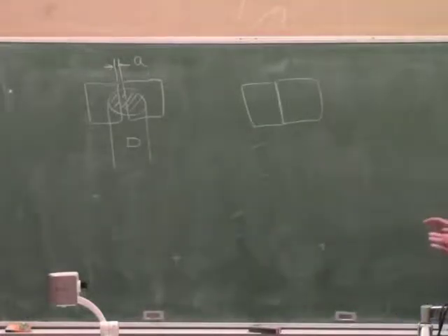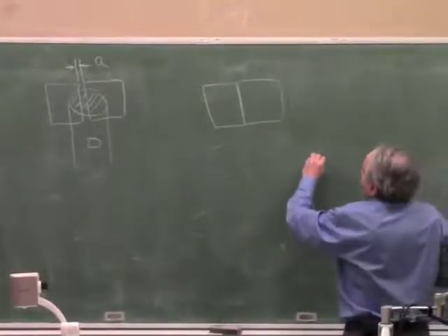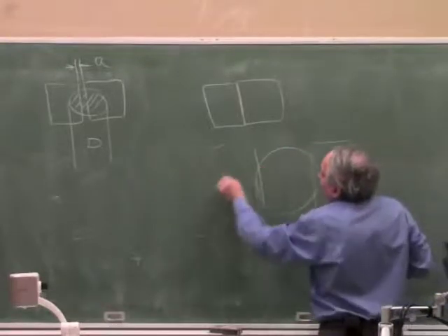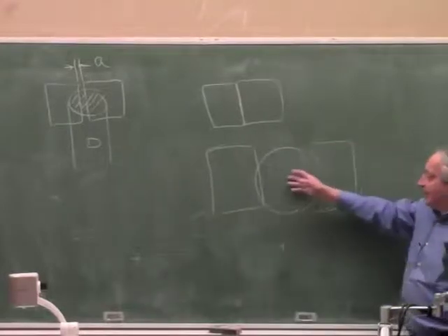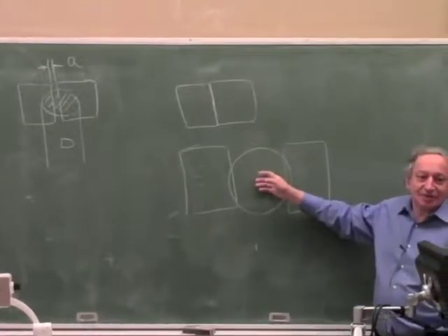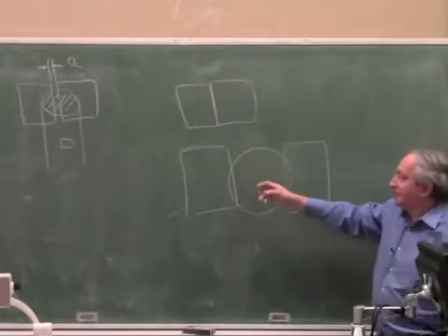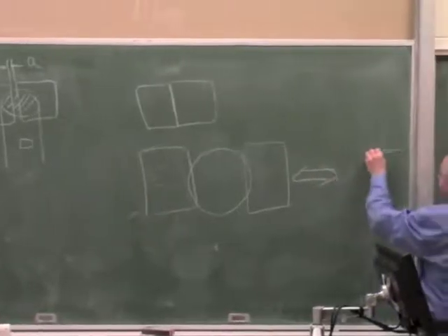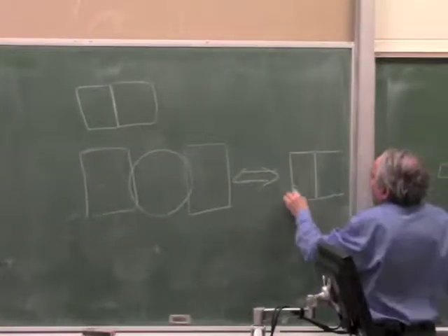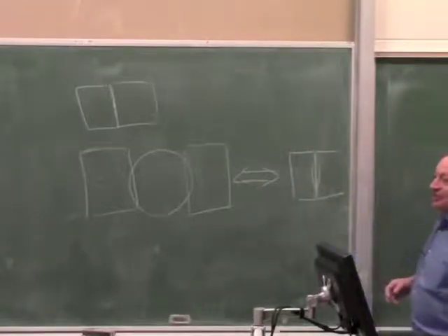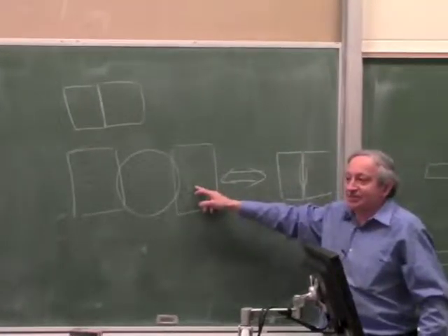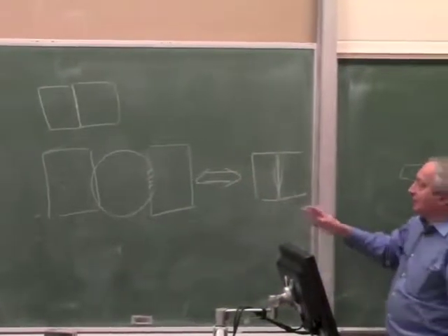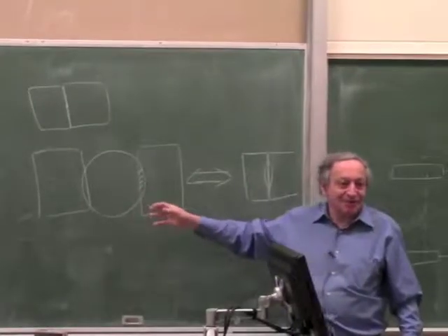First of all, it's a differential detector, so even if you make the spot this big, and you make A almost as big as the spot, you're just wasting light, but besides wasting light, you're not losing any sensitivity, right? Because this detector is exactly the same as a detector which has a very small gap and a spot like this. Because this and this, the detector sees the same thing, right? They only see this. Okay? So the only difference is you're wasting light, which is very cheap these days, from LED.